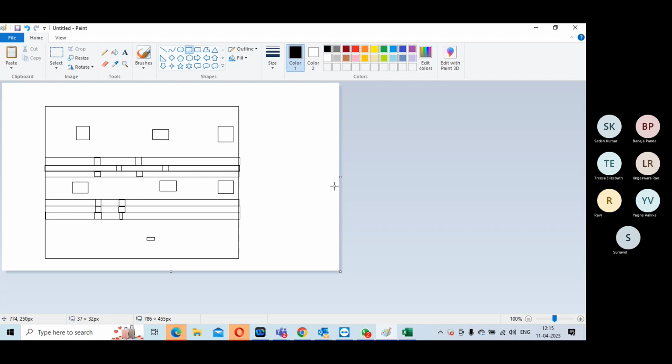Then the designer would have provided for the timing path, meaning there should be a proper register buffer so that the timing path will meet. You understand this enable, because the common cell may sit somewhere else, which has to create a high fan out tree like that.